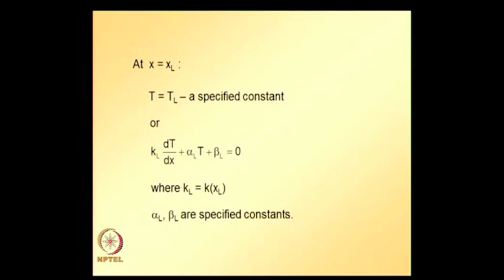Before we derive the element equations by substituting finite element approximations, if we are adopting the Rayleigh-Ritz method, we need to derive the equivalent functional. The first step is that the given differential equation is multiplied with the variation of the quantity that we are interested in, integrated over the problem domain and equated to 0.